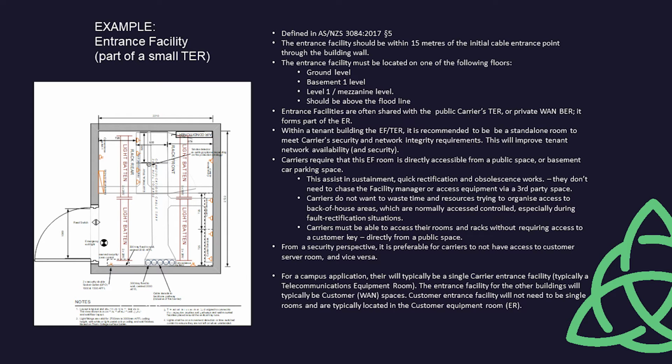Where in a multi-tenant building the room architecture differs, the base building OT network will have their own facilities, nominally located in the building core. Each tenant space will have a separate equipment room. Again, if the floor plate dictates an additional telecommunications room, the tenant may have a separate telecommunications room or a second equipment room. This is highly dependent on purpose and business requirements.